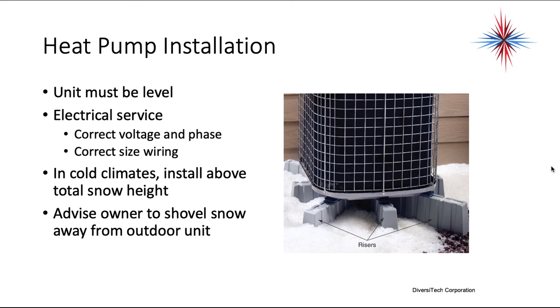Okay, we do not want it installed on risers. You want to install it flat on a heavy concrete pad, and you want to make sure it's tied down to the concrete pad. This is called wind protection. Okay, with hurricane force winds, these units will move and flip over. So what you normally do in the southern climates, especially in hurricane areas, you attach an angle iron to the base of the unit and an angle iron to the concrete pad it sits on.